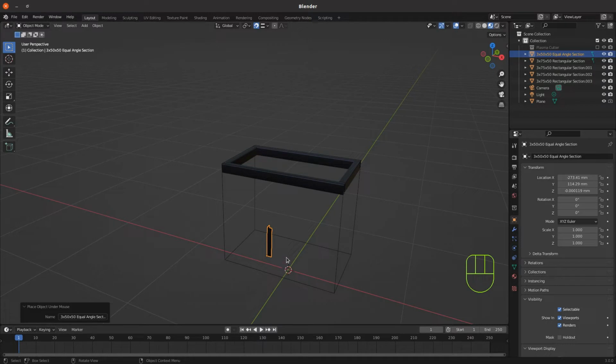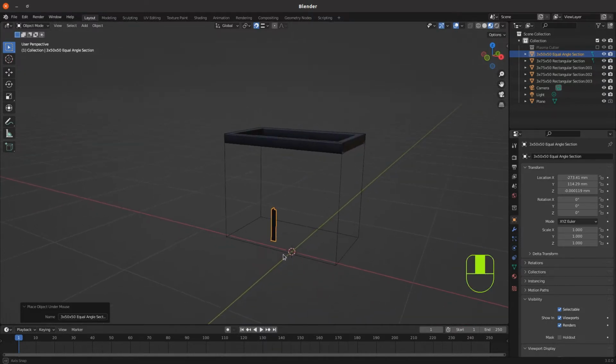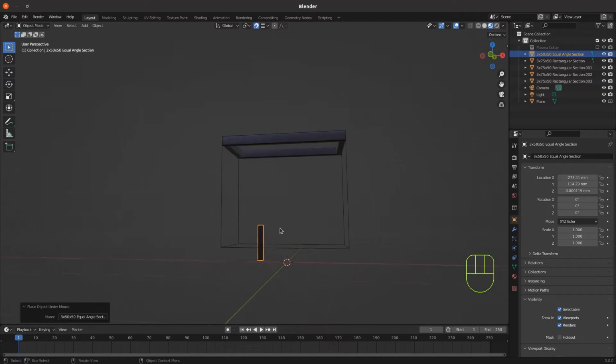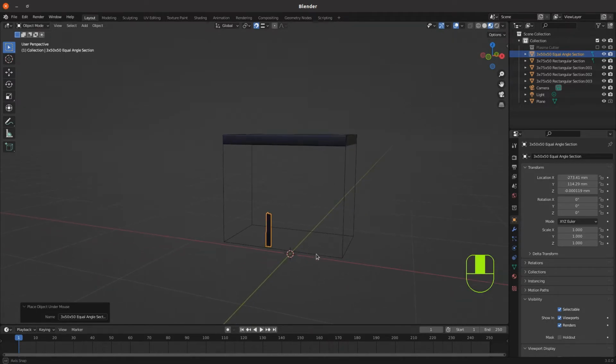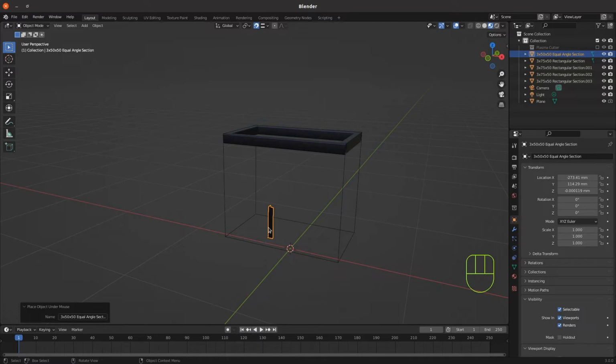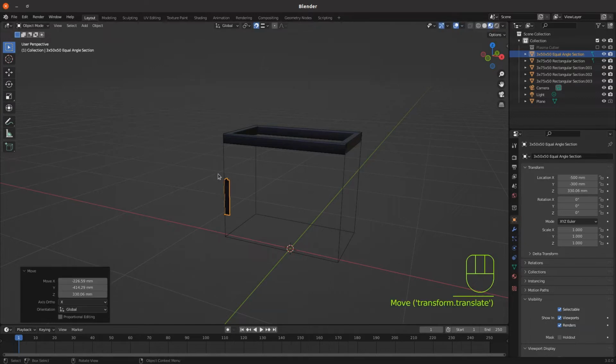So we've now got the angle iron sitting on the grid, which is below the level of the frame, and as it sits vertically, it's useful for the uprights, and the uprights have got square ends. The bottom frame will have to have mitered corners to go around the square of the bottom frame. So I'm going to first of all grab the angle iron and just snap it to one of the legs, in position on the reference frame, so it's in the position of one of the legs.